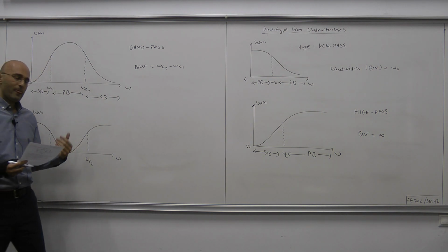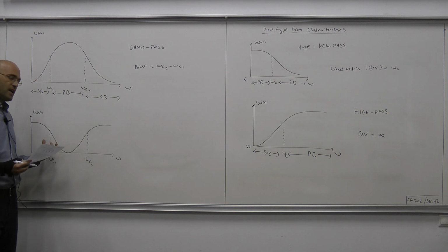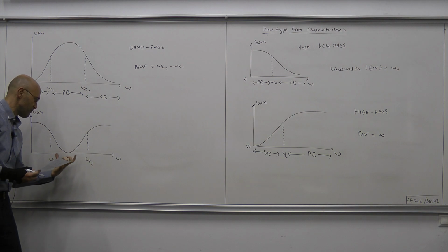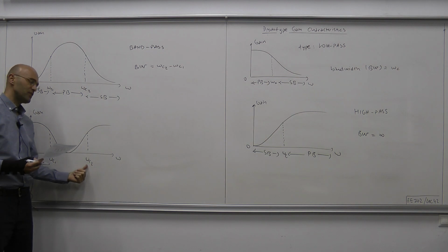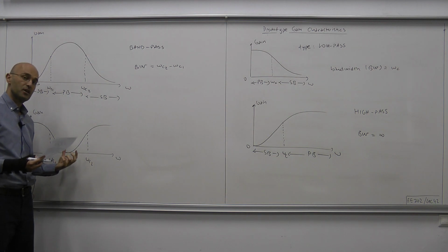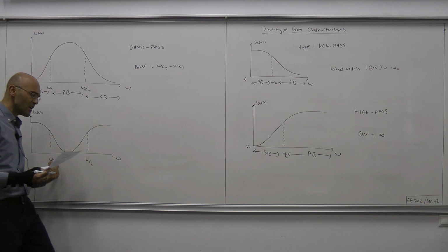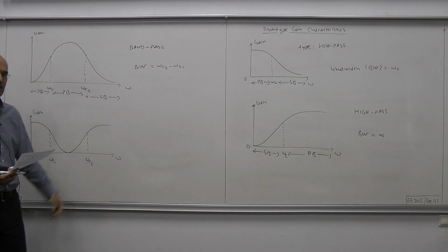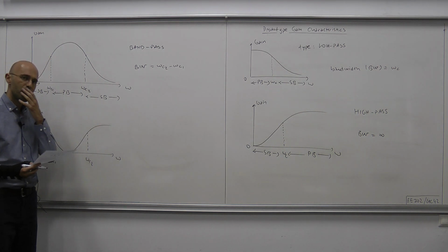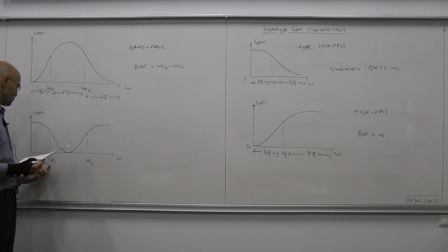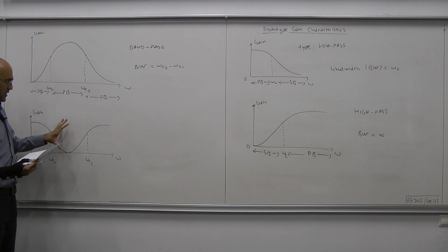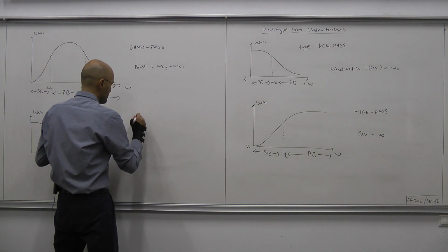This shape of the gain function makes it clear that the frequencies from omega c1 to omega c2, namely the intermediate frequencies, so to speak, are not allowed to pass to the other side. Okay, well, something passes to the other side, but it's not much compared to the very low frequencies and very high frequencies. Therefore, this type is called band stop.